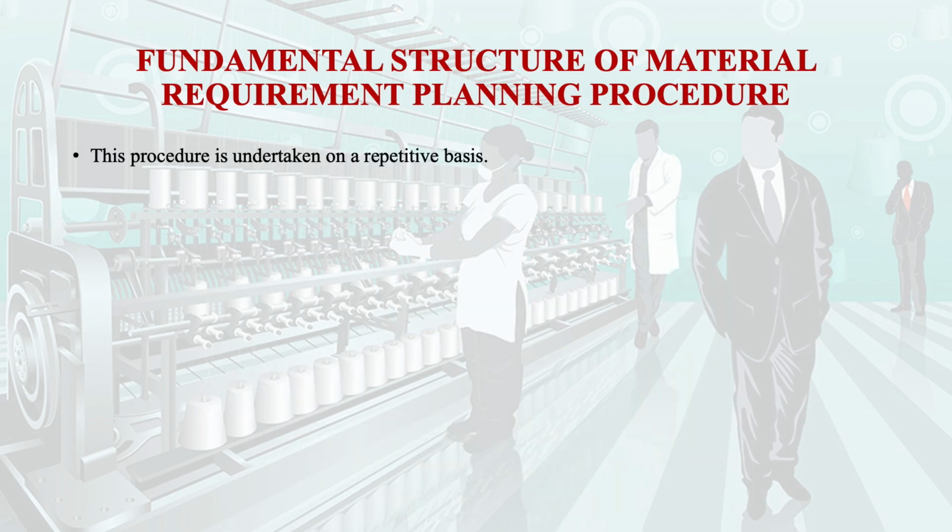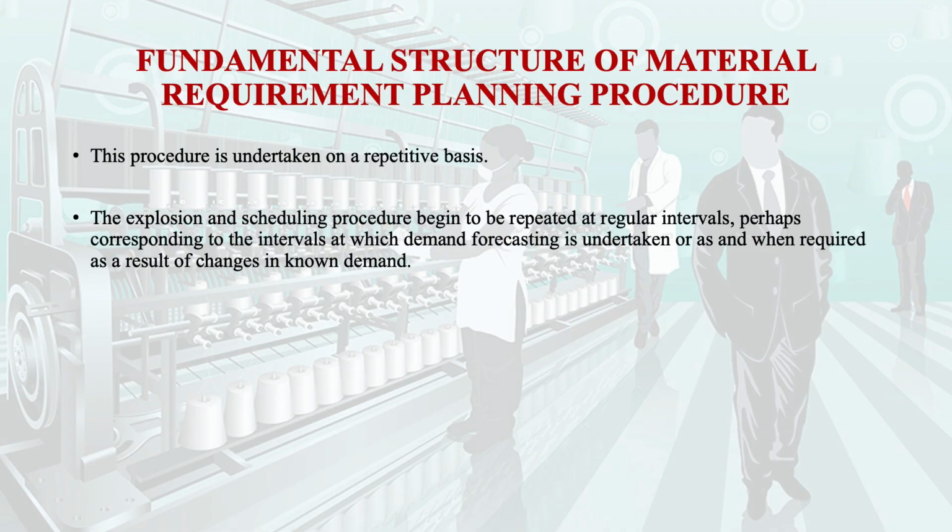it is a type of repetitive process, because the same process is repeated for each type of component or subcomponent, assembly or sub-assembly, and we call it an explosion. Just like in an explosion, the small parts are scattered. Similarly, by exploding the main component or the main product, we can get the smallest component of that particular product or the assembly.